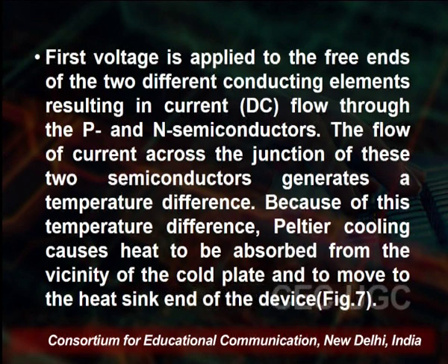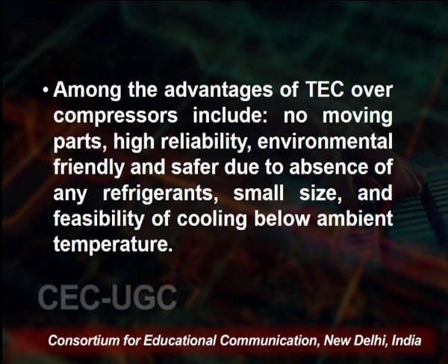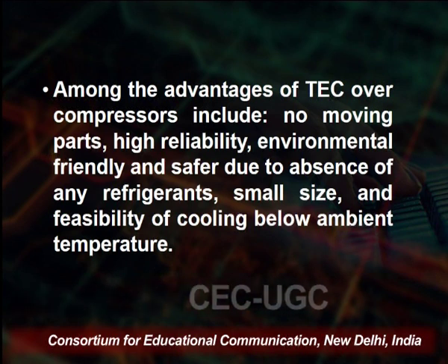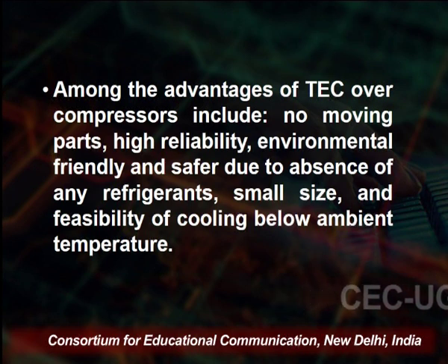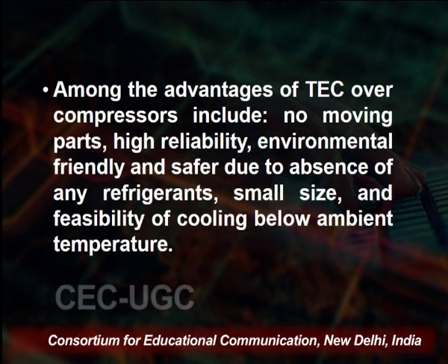Because of this temperature difference, Peltier cooling causes heat to be absorbed from the vicinity of the cold plate and moved to the heat sink and to the devices. Among the advantages of the TEC over compressors are no moving parts, high reliability, being environment friendly and safer due to the absence of any refrigerant, and small size. Cooling below the ambient temperature is also possible.